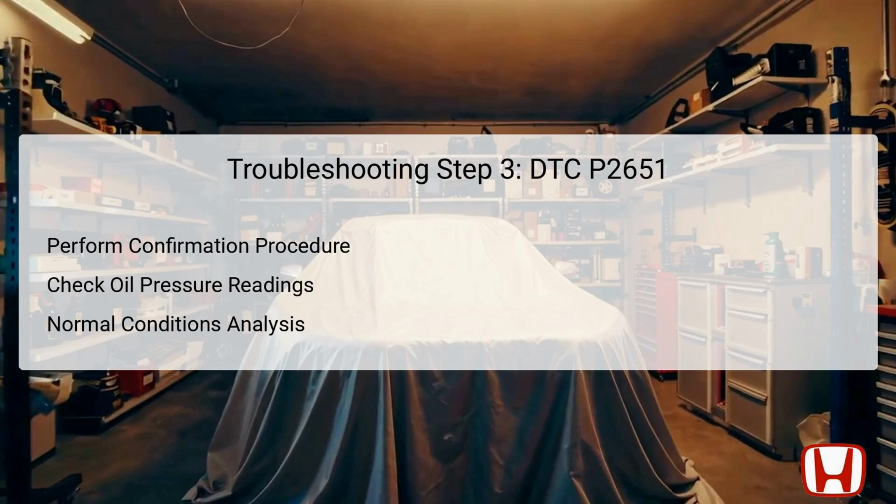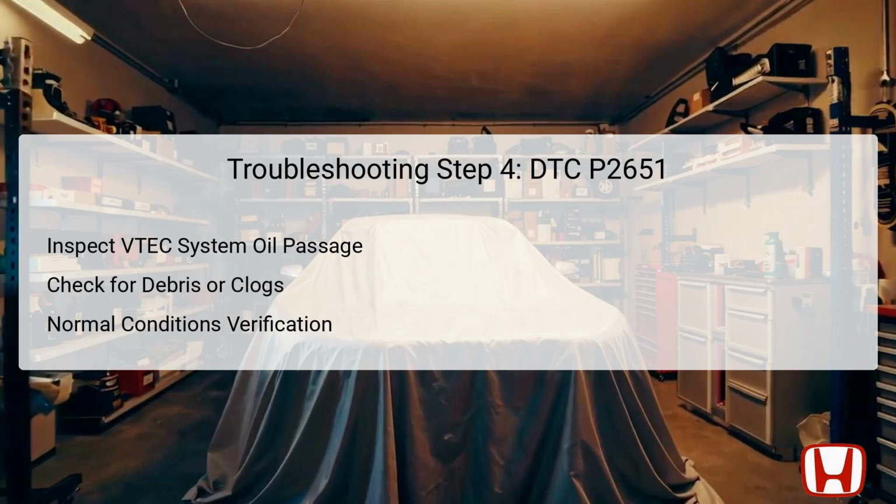If the pressure meets these requirements, the issue is likely with the rocker arm oil pressure sensor itself. Conversely, if the readings remain low or abnormal, more extensive evaluations of related components are warranted. In this step, the focus shifts to inspecting the VTEC system oil passage, as obstructions can severely impede oil flow necessary for proper engine operation.